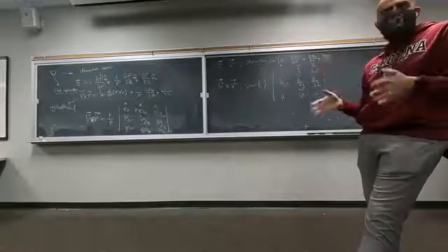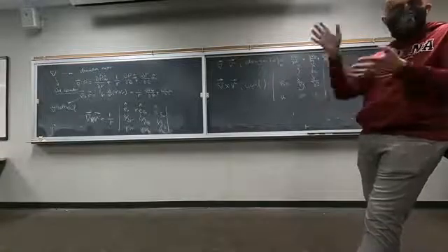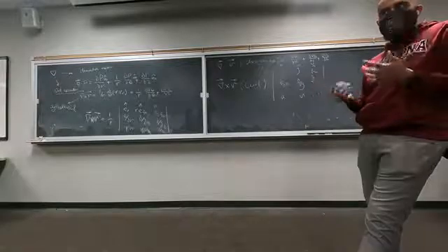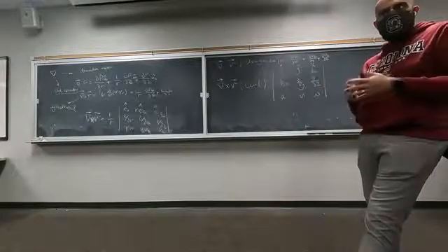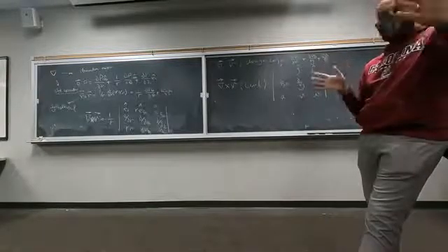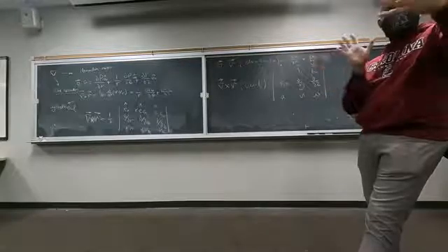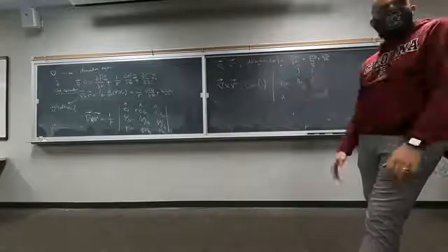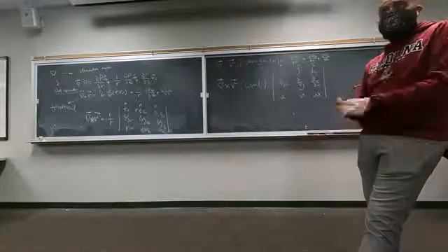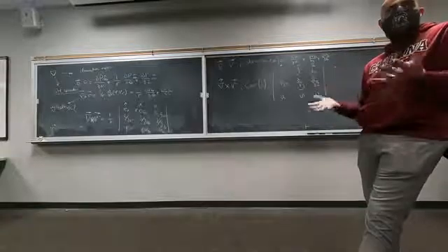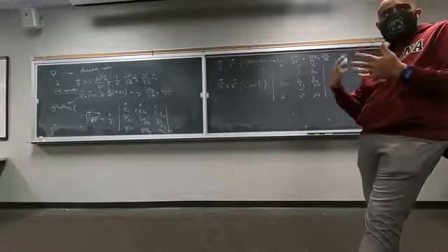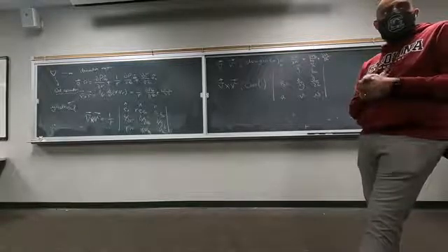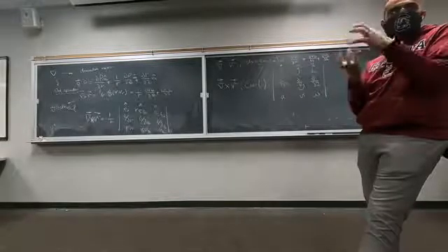You do this for momentum. You write the momentum on each surface, and based on the directions, you just have to write the force balance for momentum: sigma F in the x direction, which is the forces that are being applied in the x direction to your big, arbitrary volume, and that's it. You do the same thing for energy. The difference between energy, momentum, and the conservation of mass equation is that you won't have any mass generation inside your small volume.